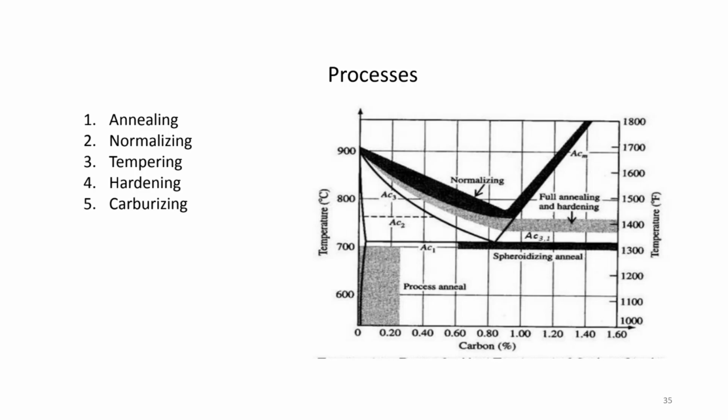Next are the types of heat treatments that are possible for steels: annealing, normalizing, hardening, tempering and carburizing. Compared to these, carburizing is the process known as surface hardening, where you are adding some chemicals as well. You will be adding carbon. So this is different from the other four.